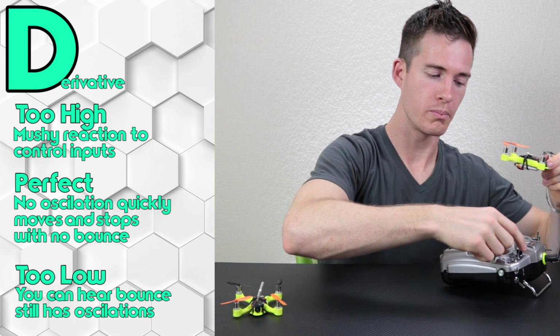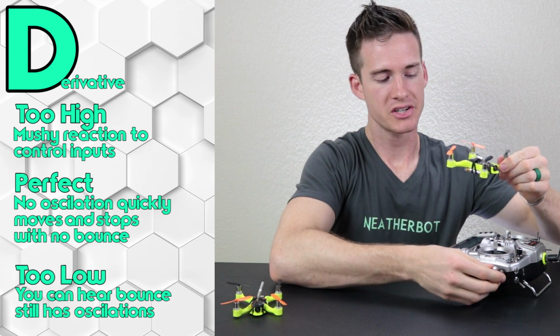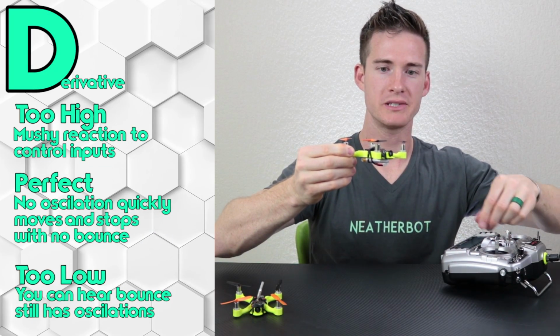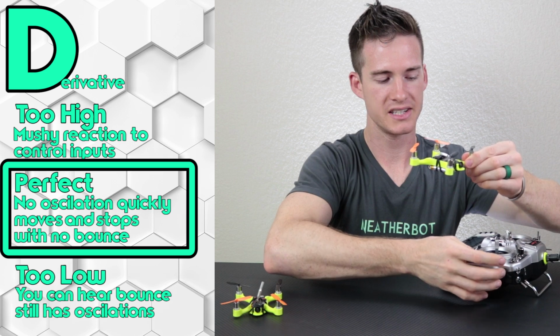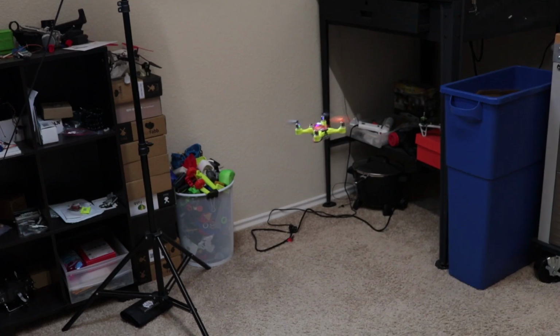So we're going to switch all the way to the down position. We start editing the D value, and we're going to start increasing D. We'll be hovering, trying those same sharp pitch movements, and we want those oscillations to completely go away. Eventually, with D going up, you'll notice that you pitch, and it's just going to go and lock.